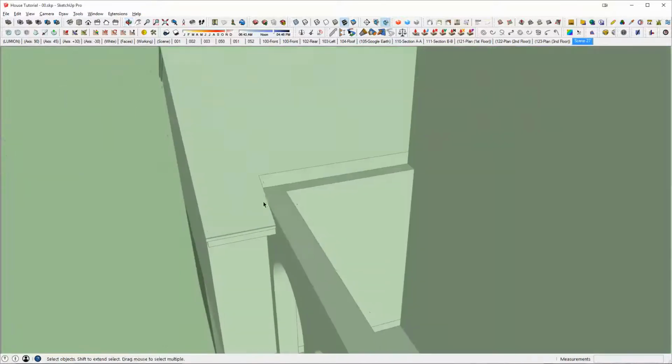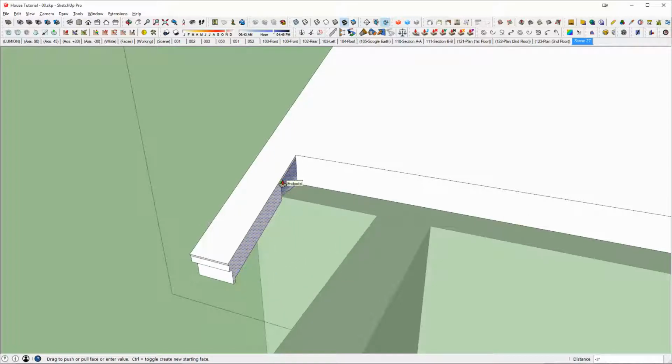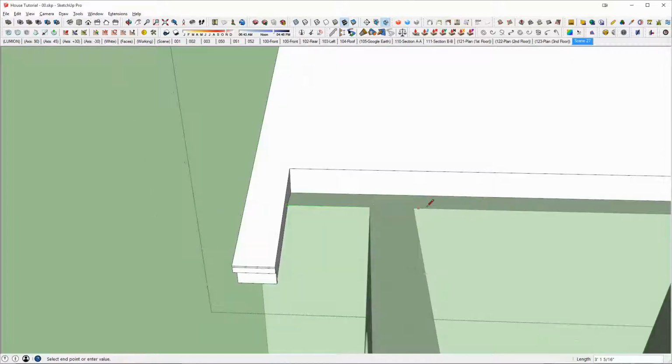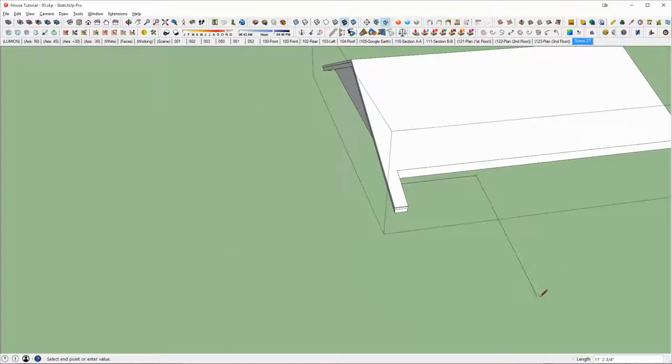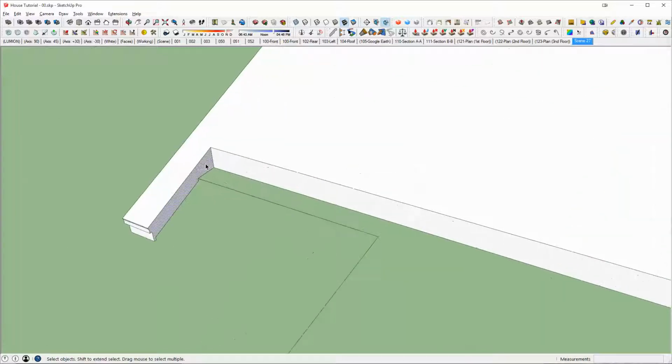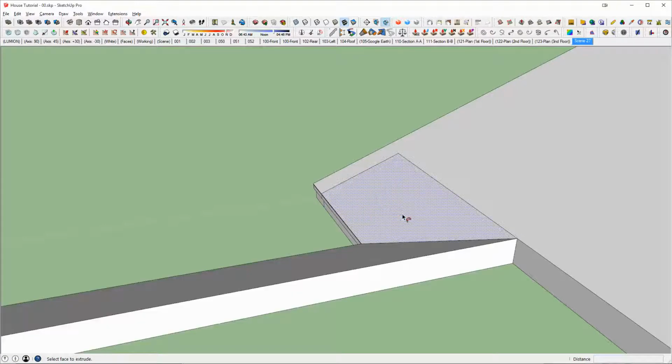By that, what I mean is I'm simply going to take this roof and I'm going to push it back. It says I can go 2 feet, so I'm going to actually run it back, say 23 inches. And I'm going to give it a line to follow. I'm actually going to go further than what I need, just to kind of buy some insurance. And so I'm going to select the path for it to run on and use the Follow Me command.